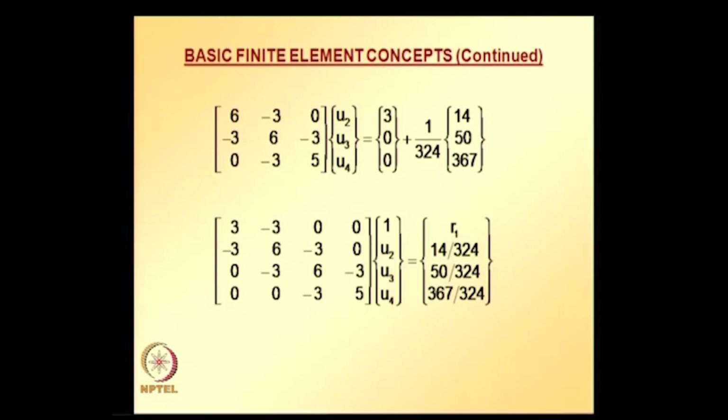using this idea, global equations obtained using the variational method are identical to those obtained using the Galerkin method, which you will see in a while. So, whatever procedure we are following here, the variational procedure, but you have seen from the examples that you looked at for classical approximate techniques, you get exactly the same solution if you adopt the variational method or the Galerkin method. So, similarly here you get exactly the same equation system if you use the second approach, that is, wherever the essential boundary condition is known, at that location in the force vector you make that component unknown.